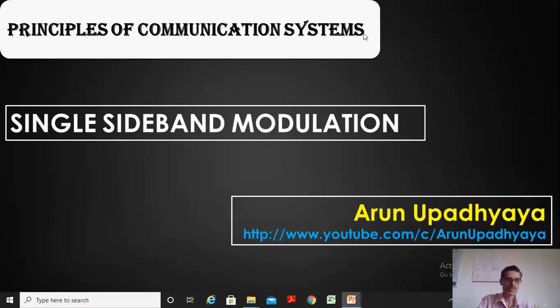Hello everyone. In this video I will explain another type of amplitude modulation method, which is called single sideband modulation. As you know, when I perform amplitude modulation, we actually get two sidebands and one carrier. If I transmit both the sidebands and the carrier, all three components, that method is called double sideband full carrier, or what we say is a conventional AM signal.